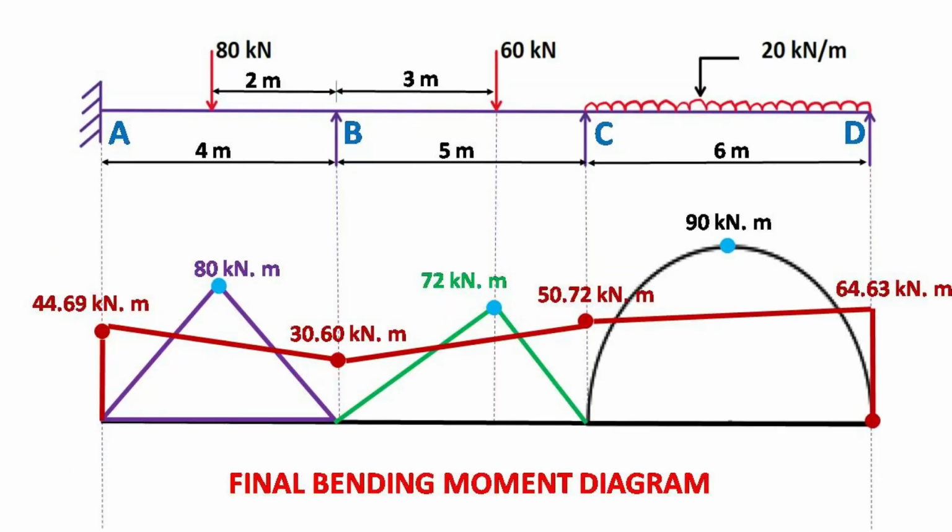Slide 12. From these calculated final moments we are drawing the final bending moment diagram. For drawing the final bending moment diagram, first we should draw the free bending moment diagram. And on that we have to plot our final moment values. Further joining them we will get our final bending moment diagram of the given continuous beam.